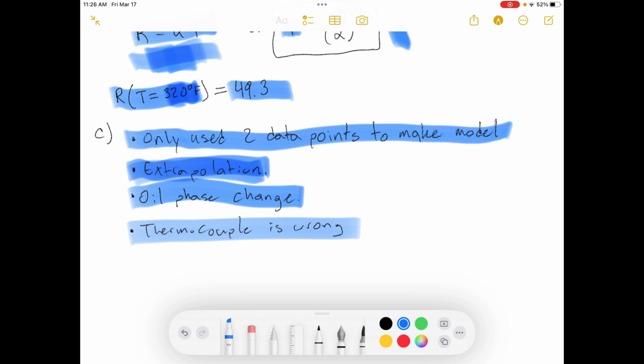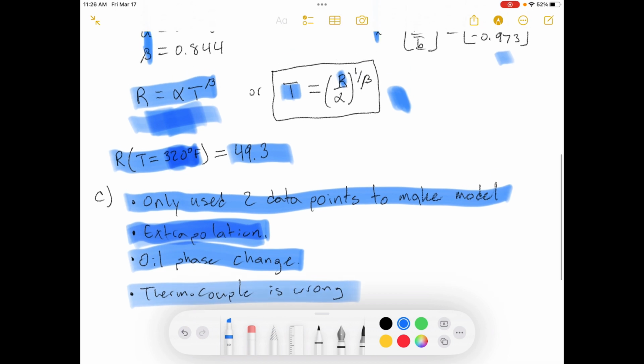You insert a thermocouple, but it's not calibrated correctly, so it's giving you the wrong value. All of those things are possible. So you just have to think through each one of those things and find different ways to check each one without affecting the others. Or you could change all of the little things and check all of them to make sure that your next experiment accounts for each one of these variables.